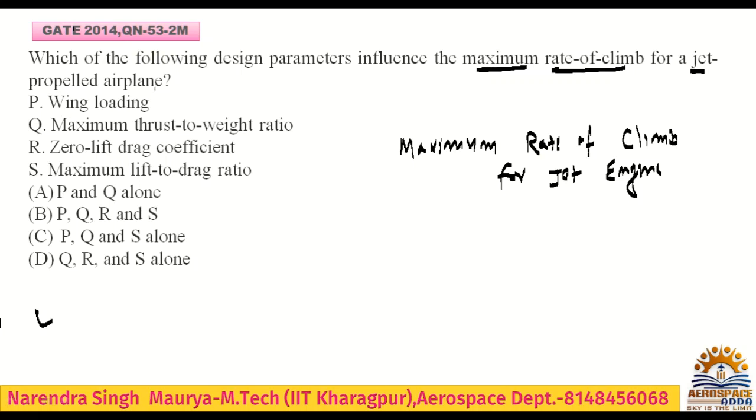See, influence the maximum rate of climb for jet. Yes, wing loading will be influenced. Maximum thrust to weight ratio, yes, it will be influenced. Maximum lift to drag also it will be influenced. Hope you understood this. And another option is zero lift drag coefficient.